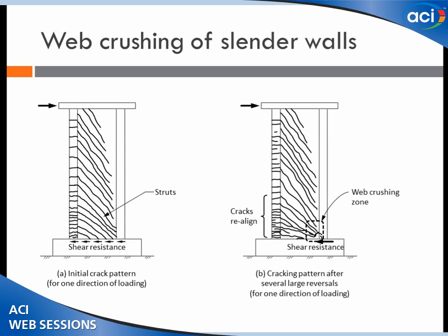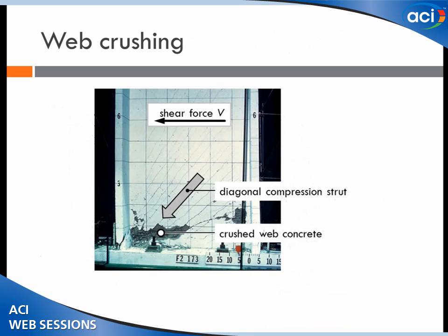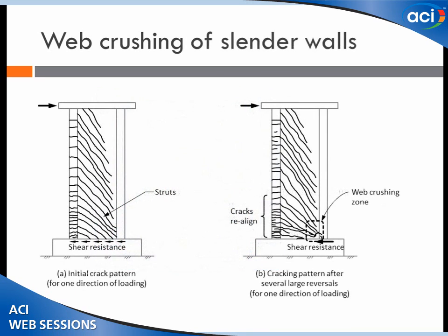Another really interesting aspect, and I think a gem of work, and I think, Tony, you worked some on this, as well as others, was looking at the web crushing of slender walls. What's shown on the left is the crack pattern that develops in a structural wall early on in the test, before there's a lot of inelastic response. And that was not supposed to come up.